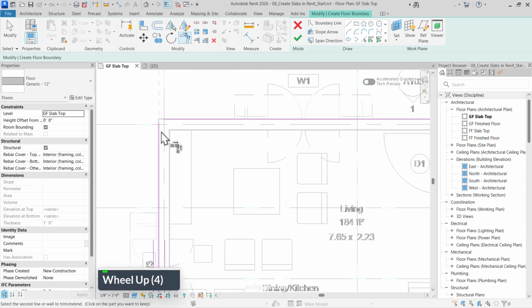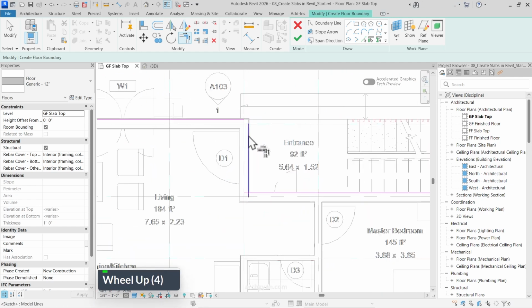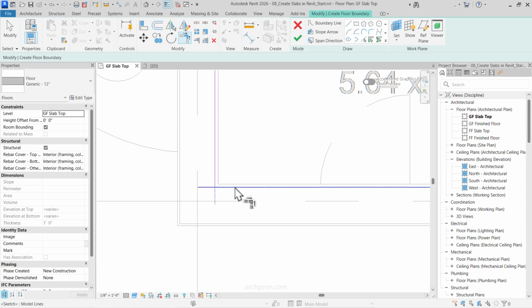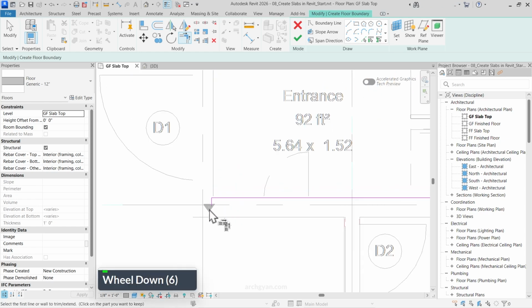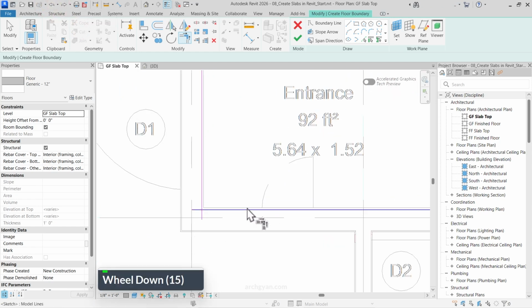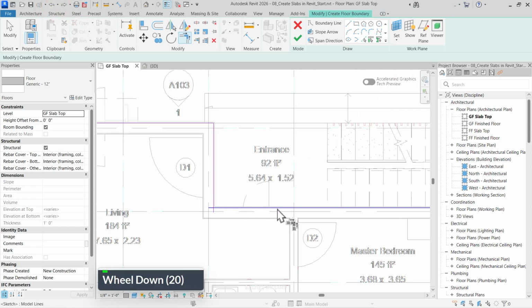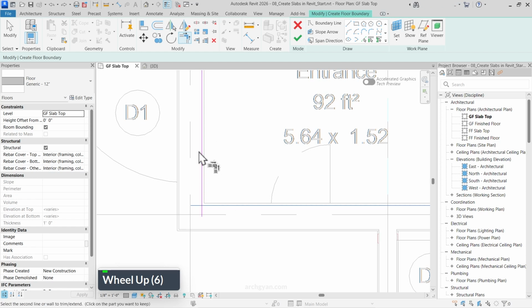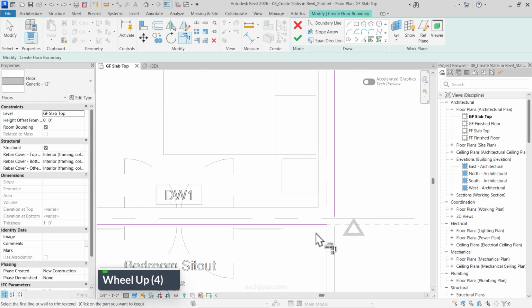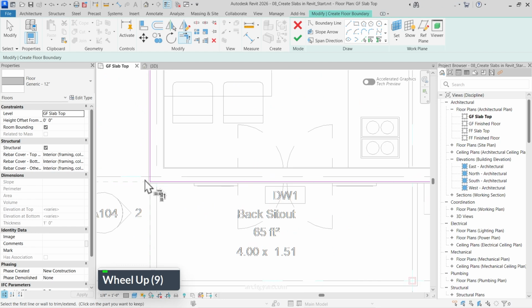So I'm going to go through the entire building and trim all these lines. Now, most students make the mistake of selecting the shorter line first and then the longer line. So you would trim it the wrong way. So make sure you trim it always by selecting the longer side of the line, which is this line here, and the longer side of this line, which is this side here, so that the shorter side gets deleted or trimmed. Perfect. So I've trimmed all my lines.